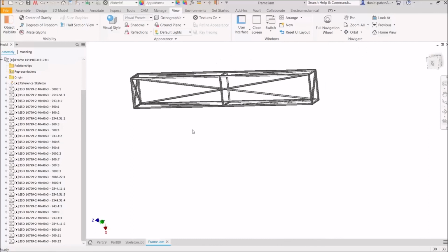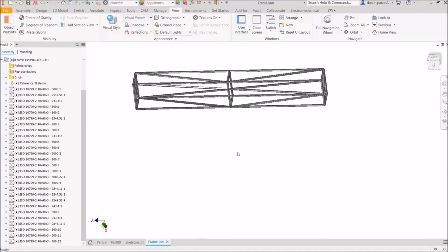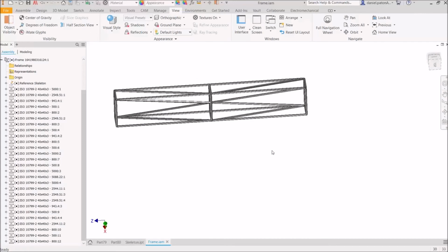Okay. Now, if you wanted to do updates like that with the 3D sketch, it does get a lot more difficult if it's purely a 3D sketch. Sometimes you can manage it okay, but you'll find that because you're working with 3D lines in a 3D space, they tend to not constrain correctly and they might shift out of place.